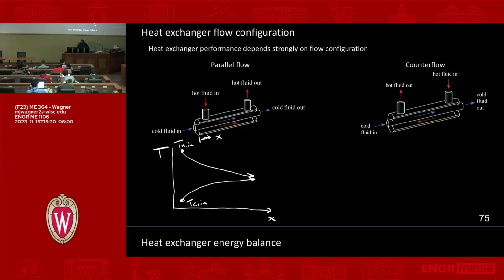Okay, so a couple things. The final temperature difference at this point would be called the approach temperature. Normally we talk about the approach temperature being the closest temperature on either side. So if it happened that closest was on the left, you'd say that the approach temperature is on the left. It's just the closest that the two fluids get to each other in temperature.